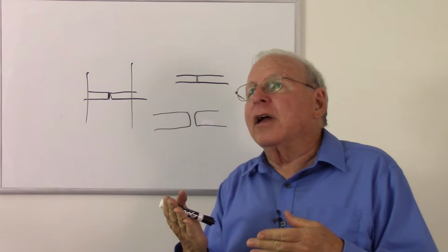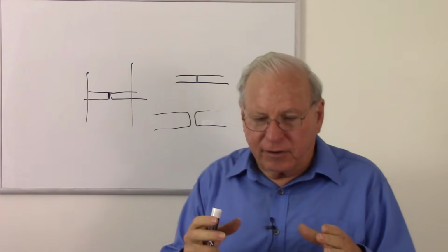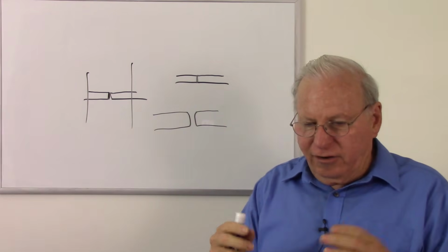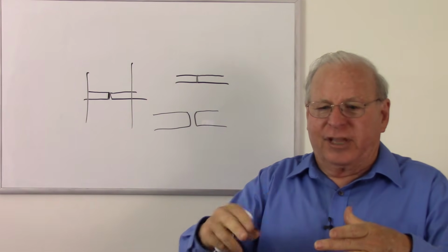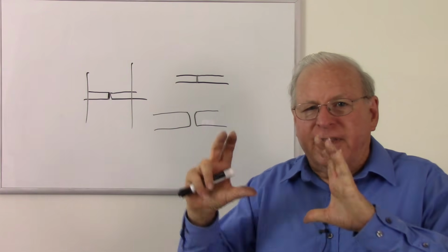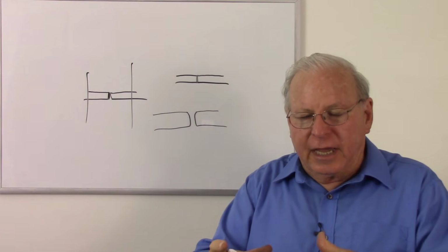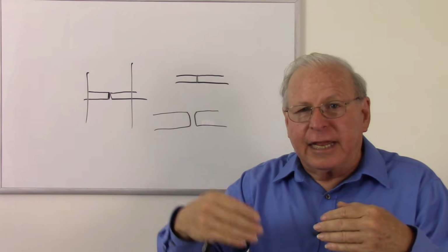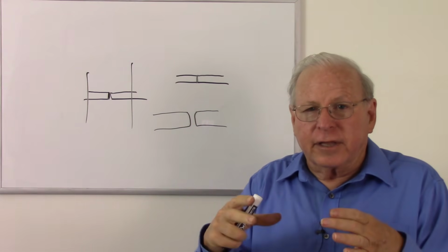I had a story: a friend of mine who used to be an optical technician was working with some optical flats, and the way you test it is you have a test flat, just a little disc of glass that's perfectly flat, no coating, and you take the flat you're making and put it on top of there. When they come together, light coming in makes an interference pattern, and if the lines are straight, then you know that they match.